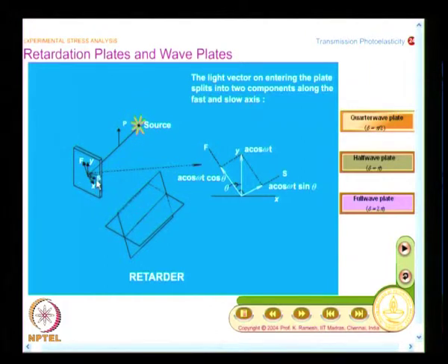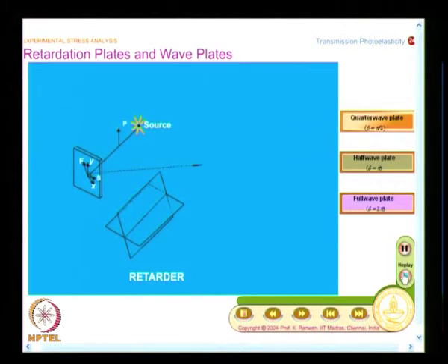So, what I have here is, I have a crystal plate. It is not loaded, it is a natural crystal, and I have this in a form of a plate. And what I have is, I have a light source and I have put a polarizer. Now, you must be familiar, and we will just see what happens. So, what you have here is, I have a natural source of light. After the polarizer, I have a plane polarized light impinges on the model.